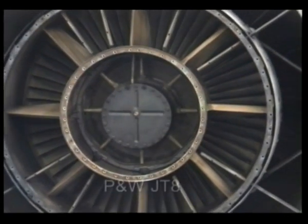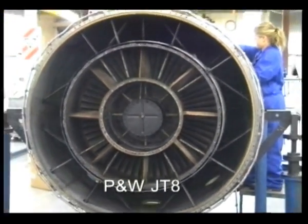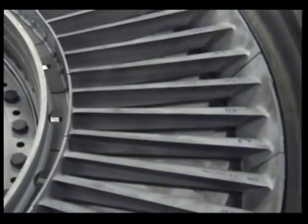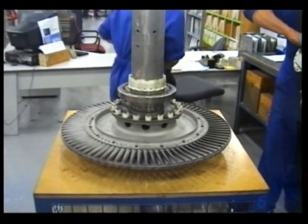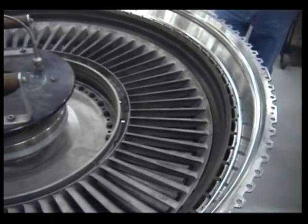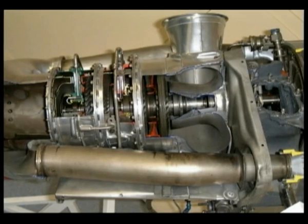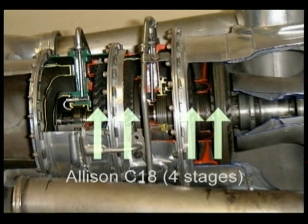To produce the driving torque required, the turbine may have a number of stages. Each stage has a ring of fixed guide vanes and a row of moving blades or turbine rotors. The number of stages depends on whether the engine has one shaft or two, and on the amount of power required from the gas flow, as well as a number of other factors. In modern engine design, the trend is towards more rather than less stages in order to reduce the stage loading.